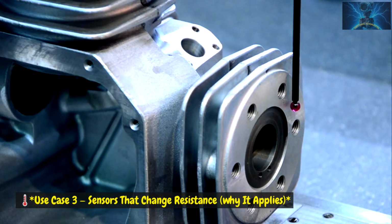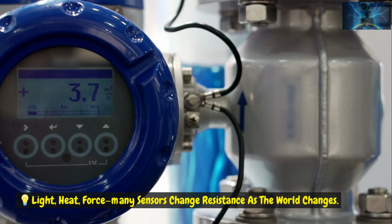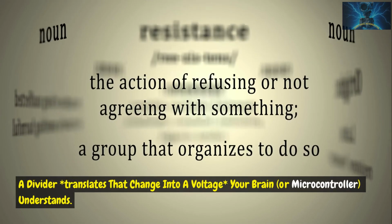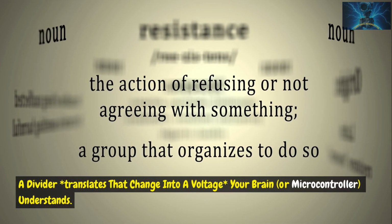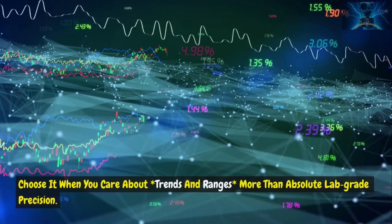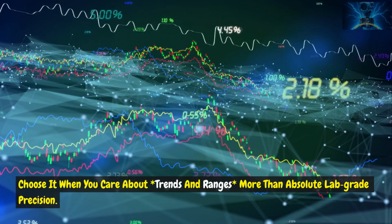Use case 3: sensors that change resistance. Why it applies: light, heat, force. Many sensors change resistance as the world changes. A divider translates that change into a voltage your brain or microcontroller understands. Choose it when you care about trends and ranges more than absolute lab-grade precision.